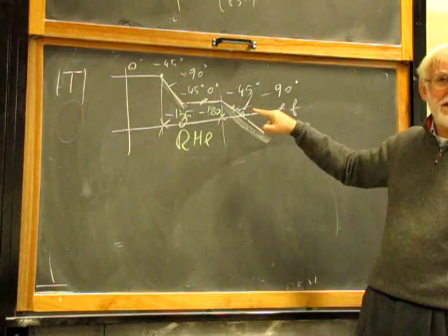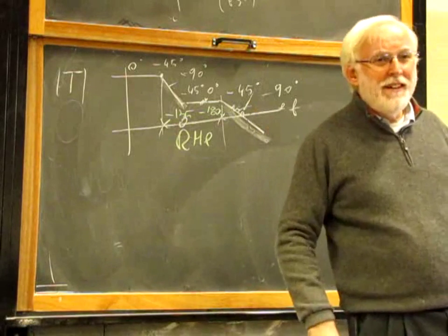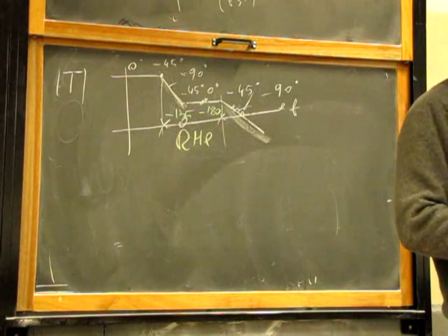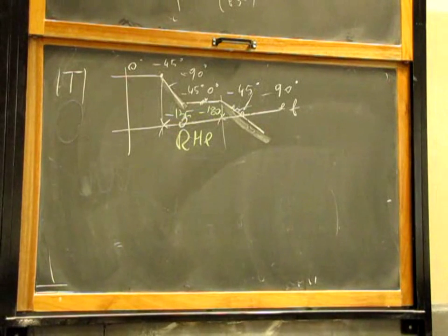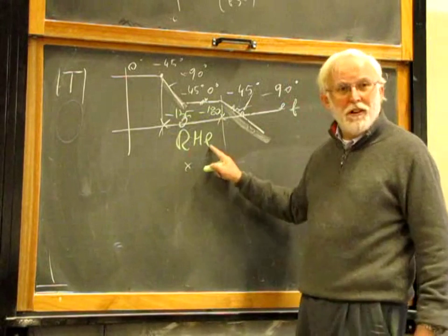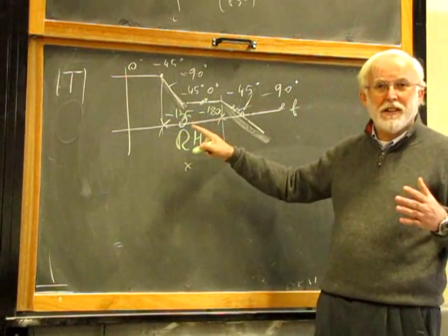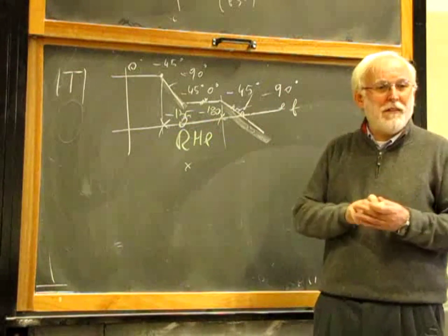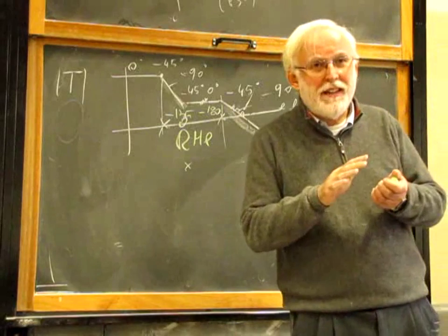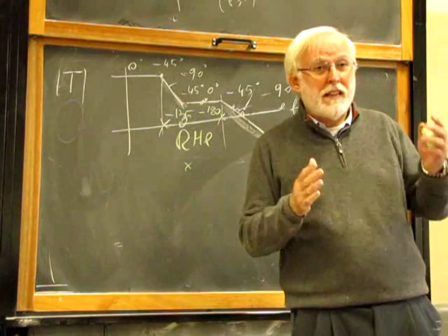How much is the phase margin? Lost a long time ago. And there is no way to compensate for it. Don't come out with the very bad idea to put here a right half-plane pole to cancel the right half-plane zero. Cancellation doesn't work in this world, because if it is not exactly on top, it will diverge anyway.